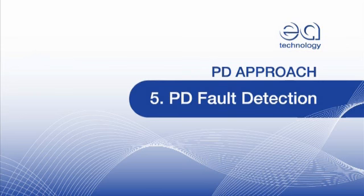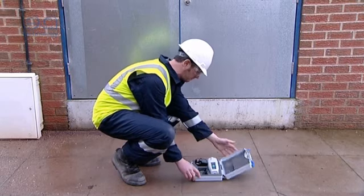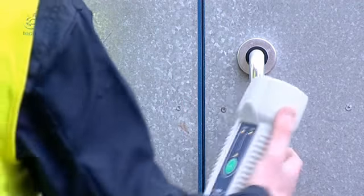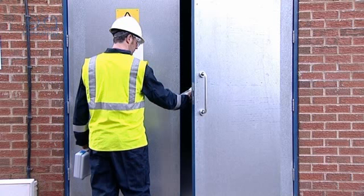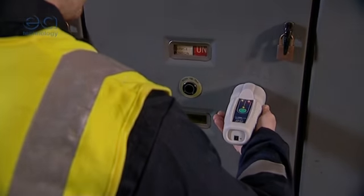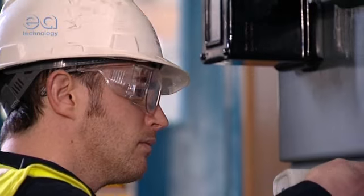PD fault detection. So, how do we find out if PD activity is at a level that needs investigating further? Simple. Use our award-winning Ultra-TEV detector to carry out a first-pass survey. It's easy to use, with little training, and very effective. Just turn it on, check for PD activity on the surface of the assets and for internal activity.